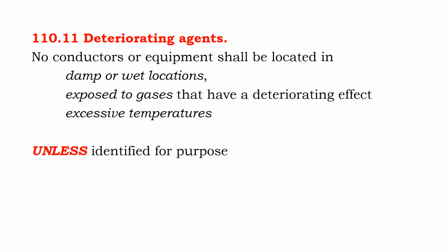Even if you end up doing 75 C calculations, just keep in mind that if you're trying to optimize your cost by designing all the way up to the cheapest wire you can possibly select for the job, that is a path towards mistakes. It's better to over-engineer and think about what you're doing.